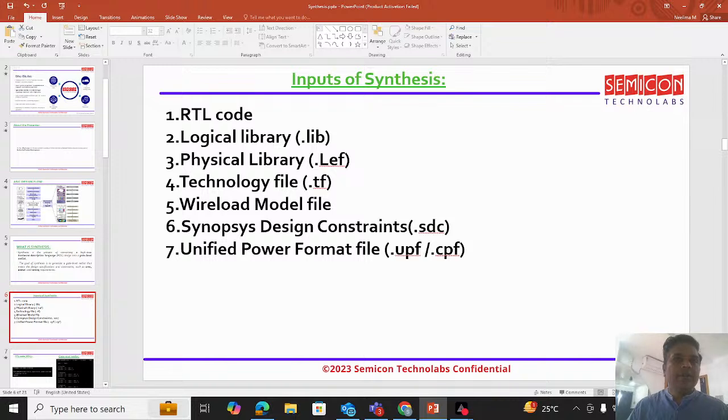So in general, once we divide the entire logic into multiple portions and keep each portion in different power domains and voltage areas, and individually turn off these power domains and voltage areas, the power consumption automatically comes down, because logic is not switching and is completely turned off. Even the leakage power consumption is zero. That's the intention behind going with either UPF or CPF, right?